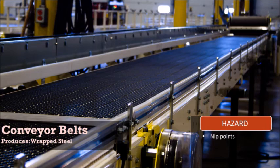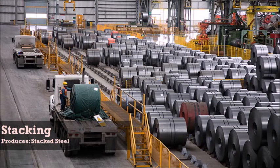Use guards on pinch points on rollers and wheels and between the conveyors and receiving table. Provide adequate guardrails along the sides to prevent objects from falling off. Provide retarders if heavy objects are conveyed. Ensure there are warning devices near the receiving areas if you cannot see the package moving on the conveyors. Ensure draft checks are installed where conveyors pass through firewalls or floors.